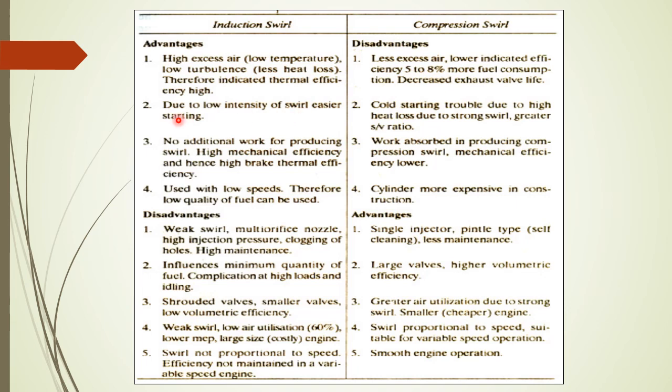Second advantage: due to low intensity of swirl, it is easier for starting. In compression swirl there is a cold starting problem, which is due to the high heat loss when the air is moved from the main chamber to the additional or divided chamber.